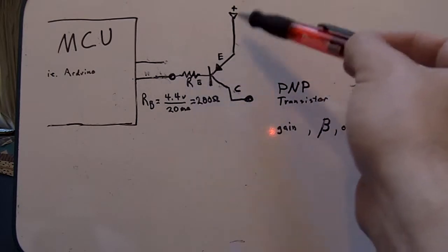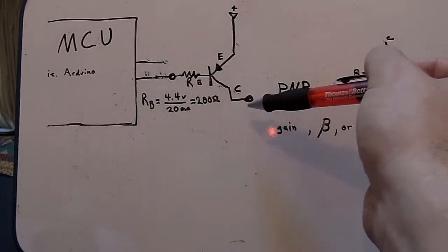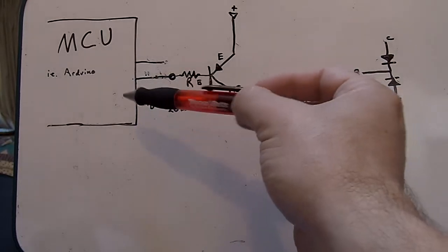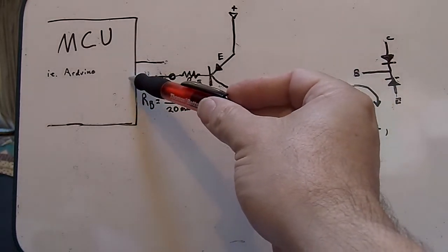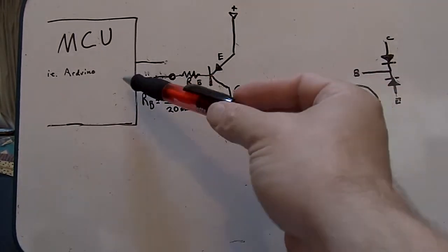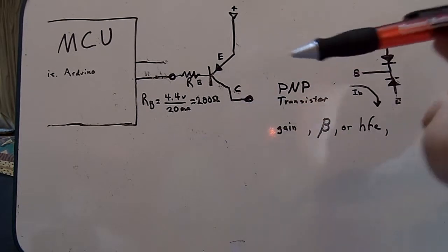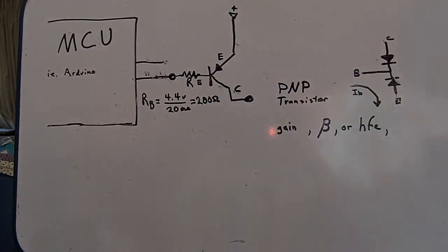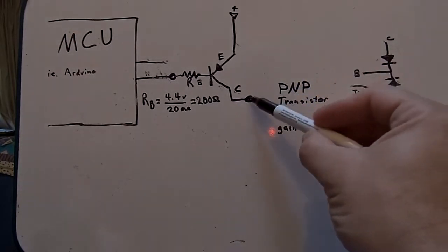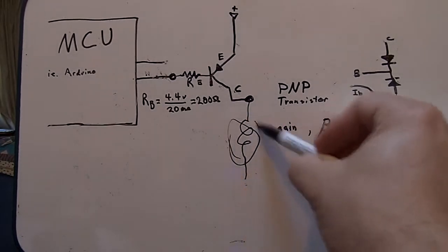But this would be giving me a higher current output and an inversion from my output pin. My pin would be inverted, high versus low would be inverted over here, but I'd have a lot more current capacity than I have here. So I could pull something like an incandescent light bulb, and then maybe that car headlight again like I was saying, or something like that. Incandescent light bulb.